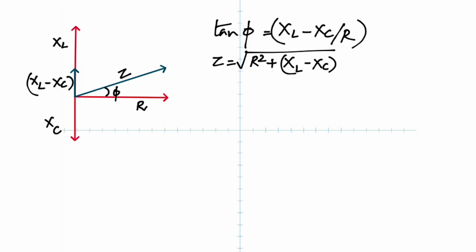So that's 2 parts to it. And at resonance, you know this part becomes 0. So impedance becomes equal to resistance at resonance. I've not written it, but you got to know that. And also at resonance, phi is 0 because XL and XC cancel out. That's why they became 0. So at resonance, the phase difference is 0. Just know that, okay? I've not worked out a problem with that, but that's very important, and try to work it out carefully, find XL, XC and all that.